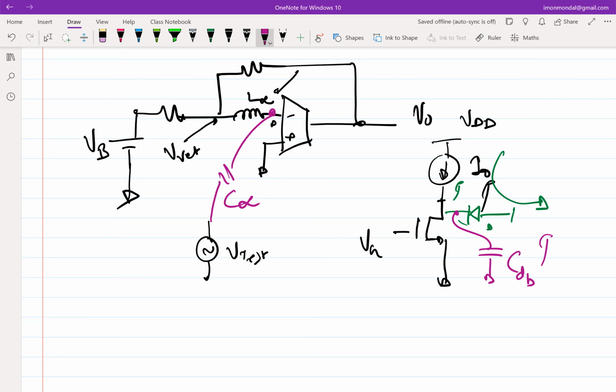Then yes, when I say the transistor is not shut off, what I mean is that through the channel between drain and source, there is no current. But if you let's say put an ammeter just around the drain of the transistor, you will get some reading. But that current is not flowing into the channel. That current is either flowing into the reverse bias diode or it's flowing into the CdB, and those are things we haven't considered till now. Okay.